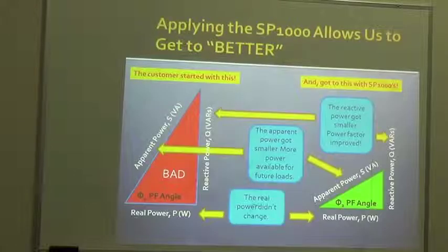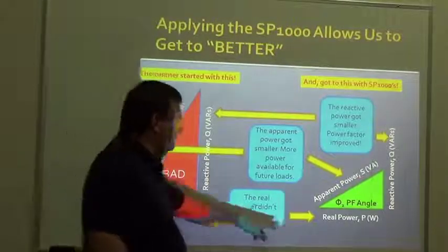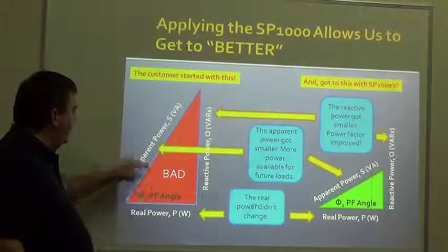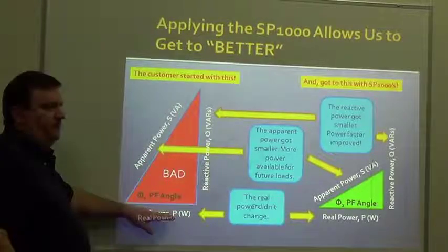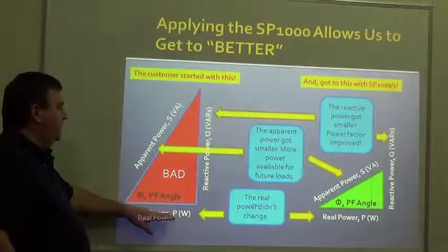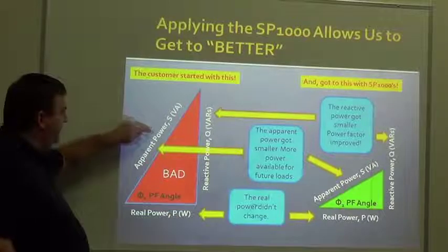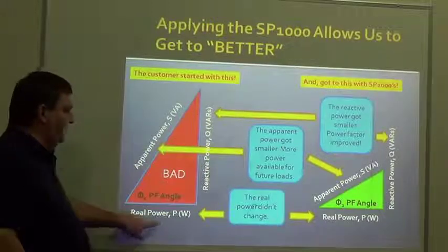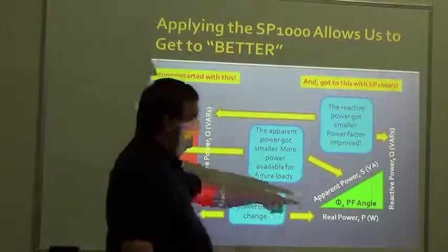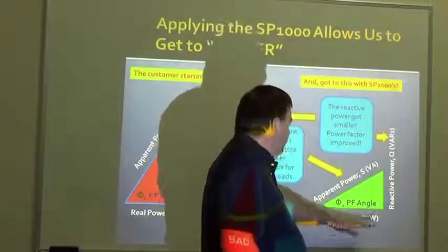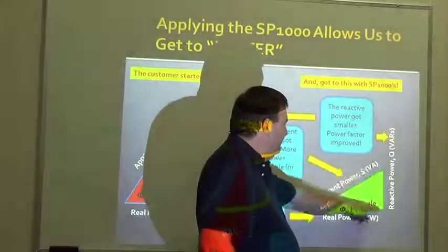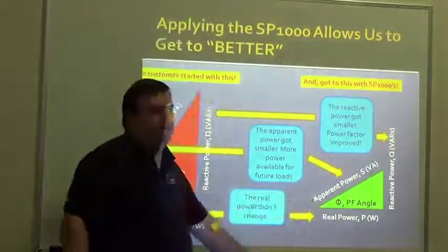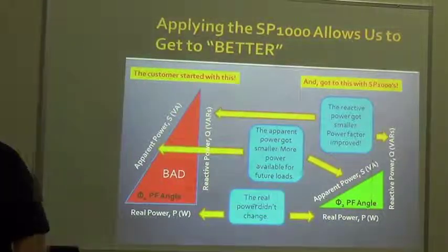Over here, we've got a fixed load we're working with. What we don't want is a situation like this, where we've got to have more available to be able to drive our equipment. If our reactive power is bad, then we're paying a lot for this in infrastructure, and we're paying a penalty on this to be able to use it in the plant. This is a much better approach. We're still able to run our plant with the load we have, but we're managing our power, which means we've essentially taken the stress off of our plant, therefore I can add more load.